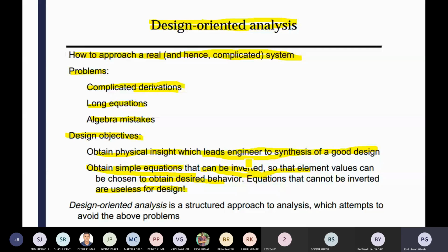When it is working with the RHP zero transfer function, your denominator has two roots, meaning the converter has 2 poles, and your numerator has one positive side zero and another negative side zero. So 2 roots are there, one in your right hand plane and another in your left hand plane. Normally left hand plane roots we consider stable.